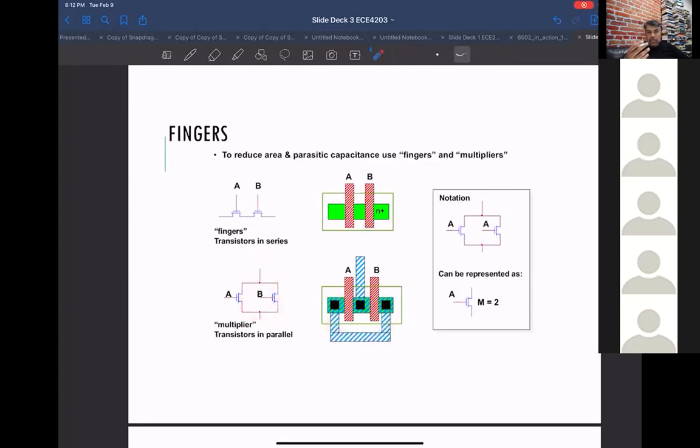Now, NMOS transistors are symmetric. So you could think of this drain and source as being either one of these. This could be the drains of both transistors, or it could be the sources of both transistors. But you can only have one be the joint drains and one be the joint sources. For one of them, it's more critical to have a low capacitance node.